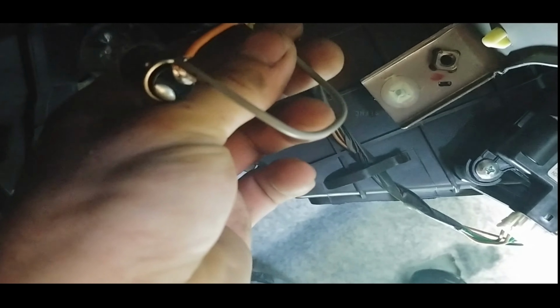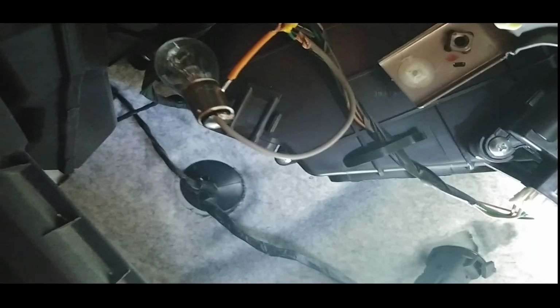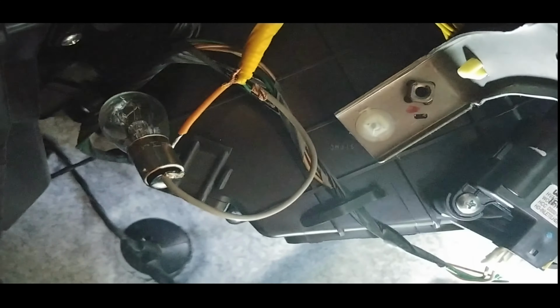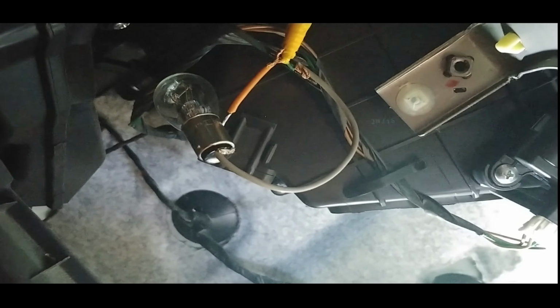I've got to try to find out why the connectors all broke. It's not good to just repair airbag wiring, but in this case, because this is a used car, they might want me to do it. I'll give you guys an update on what we end up doing, because typically I would replace the whole harness for this one connector, and that's my personal preference. But I'm not the owner of the vehicle, so we're going to give them the 2 options and see what they want to do.